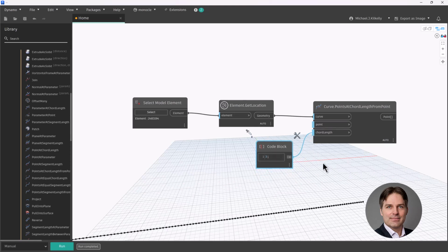Now I just need that point to kind of hit each of my parking stalls. So 3 feet should give me enough. If it were a smaller element, I might want a smaller value here, but I think we're good with 3 feet. So now that we have our check geometry, what we want to do next is get our parking stalls.